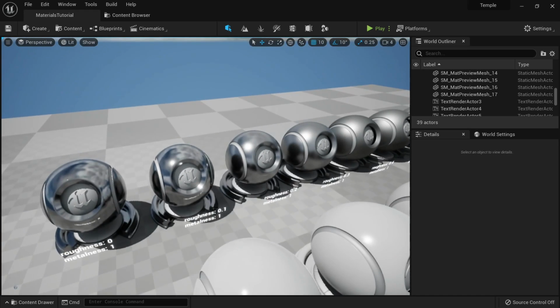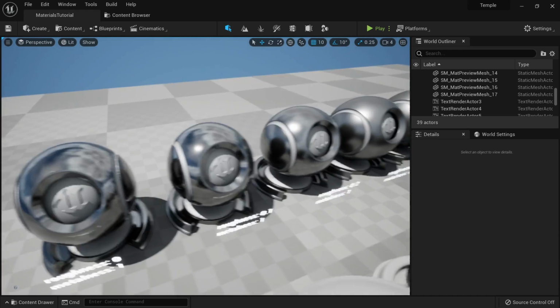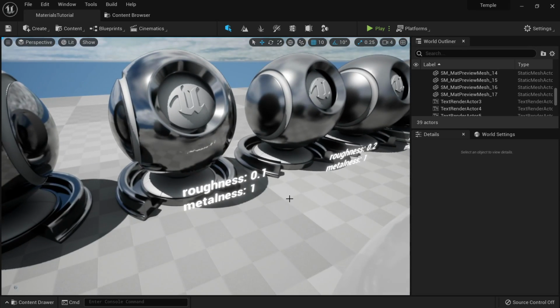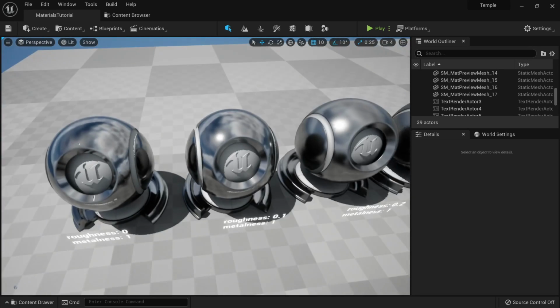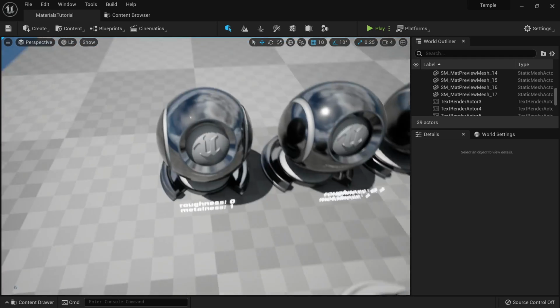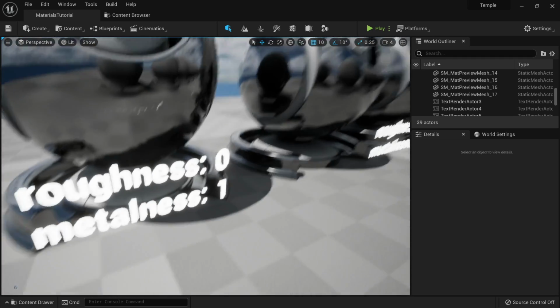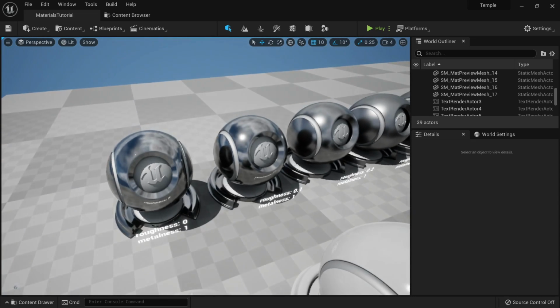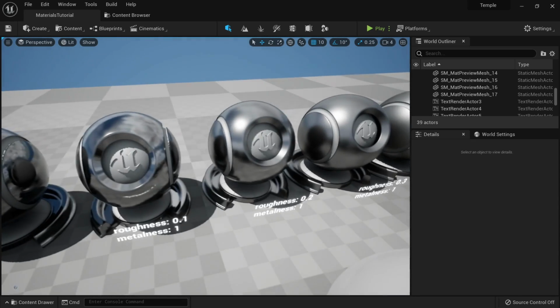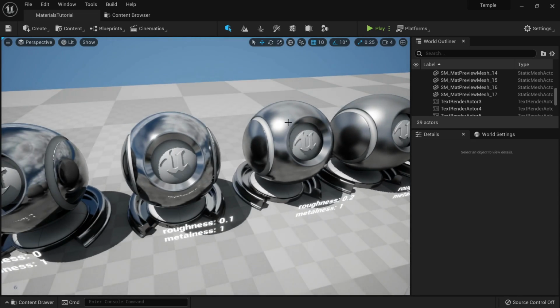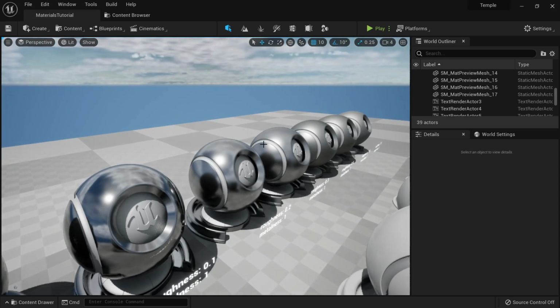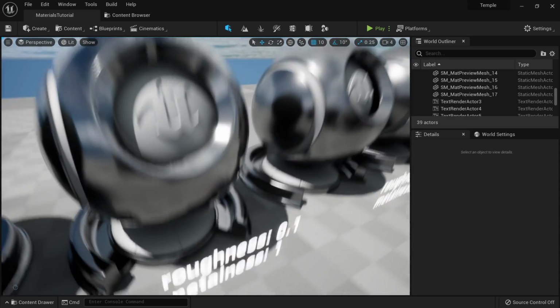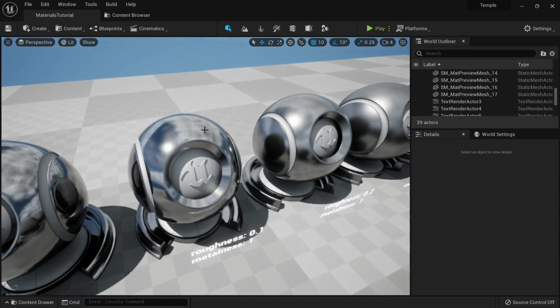Technically, you could try to change the metalness to have something like 0.5 or 0.6. However, this system is created so that the metal should only be white if it's metal, so that you have the most accurate result. However, this is not rocket science, this is just a guideline. If you want, of course, the most realistic results, make sure you have your metal at 1.